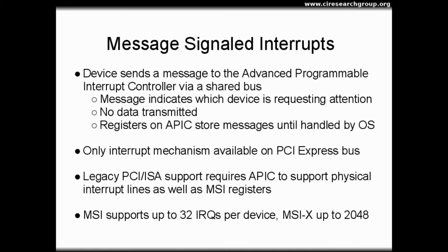This is the only interrupt mechanism that's available on PCI Express buses. There are no hardware interrupt lines. However, a number of motherboards still have interrupt lines, physical interrupt lines, and have physical PIC pins so that they can support legacy devices. There are a number of specialty legacy devices still in use that need to be supported.